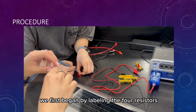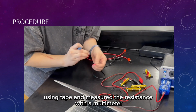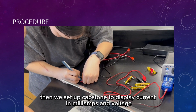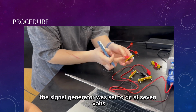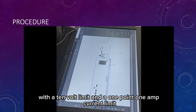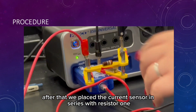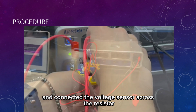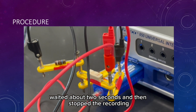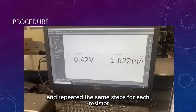We first began by labeling the 4 resistors R1 through R4 using tape and measured their resistance with a multimeter. Next, we built the circuit according to the schematic. Then we set up Capstone to display current in milliamps and voltage. The signal generator was set to DC at 7 volts with a 10 volt limit and a 1.1 amp current limit. After that, we placed the current sensor in series with resistor 1 and connected the voltage sensor across the resistor. We clicked record, waited about 2 seconds, and then stopped the recording.